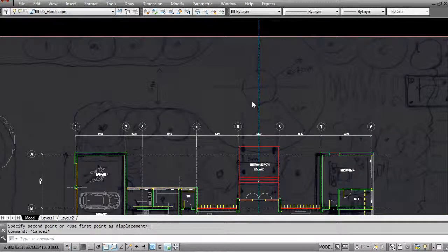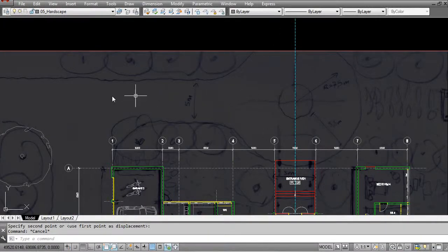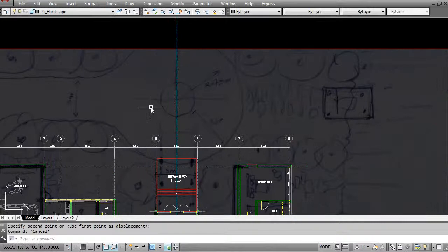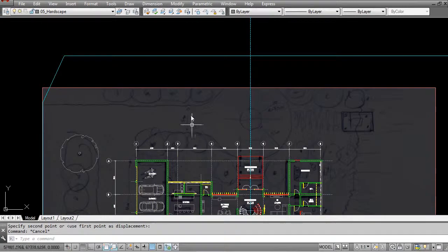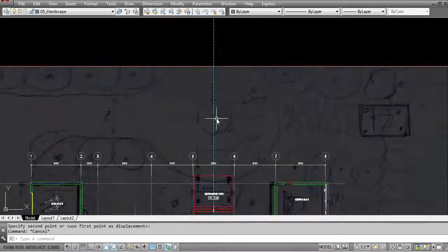The main consideration you want to have when doing these types of road axes is to have a look again at NEUFERT and see what the standard dimensions and radii are for these types of turning circles. So for example, here I've already written that the radius should be no less than 7.5 meters. We should have a road that's no narrower than 5.5, and here we should have a road of 5 meters. So you can start drawing all of this in.